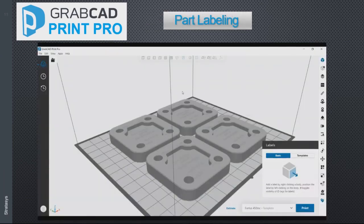All right, now I'm going to demonstrate the labeling feature that we have in GrabCAD Print Pro. What this will do is it allows you to either emboss or deboss lettering or numbers, alphanumerical characters into the surface of your STL file. So I have these 4 parts here. This is a manufacturing fixture, so a part fits onto this part, and then some drill bushings get pressed into here to allow them to drill a hole and then tap the hole. The customer wants me to serialize these parts, and they also want me to mark them with the manufacturing date.